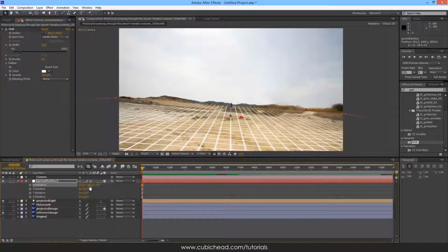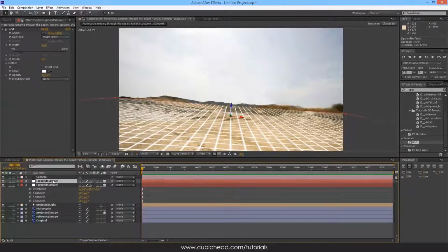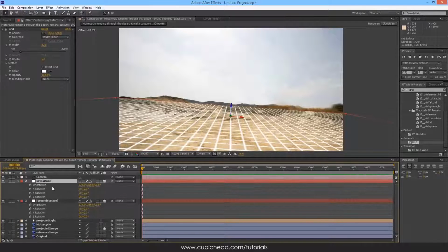Okay, for these hills, the background, I'll mix them with the sky. Now to make the sky, I've got the ground. I'll duplicate this. Okay, rename this to sky. From now on, it's going to be much more easier. Actually, setting up this scene for the 3D planes is easy because I've got two planes. But for a more complicated perspectives, like some internal views, like in a room, it's going to be in some cases a bit more complicated. But all you need to do is to change the depth of the planes and basically move around so you'll get the best perspective you've got.